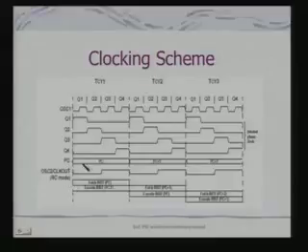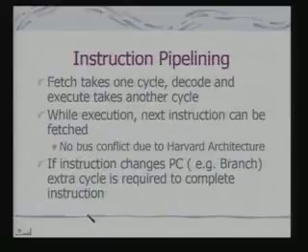So, if I go to the previous slide, you will find exactly that is what is happening. In this Q1, the PC is incremented, and between this Q1 to Q4 in the next cycle, the instruction is getting executed. This is typically how the instruction execution takes place in PIC. So, obviously, I can have instruction pipelining.